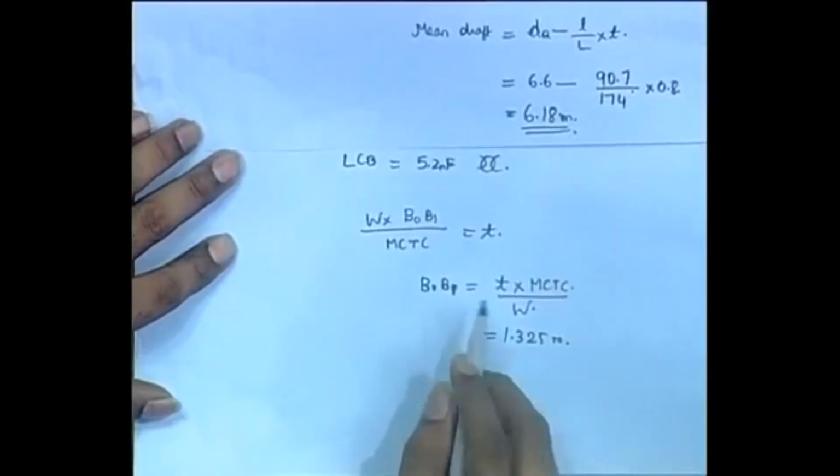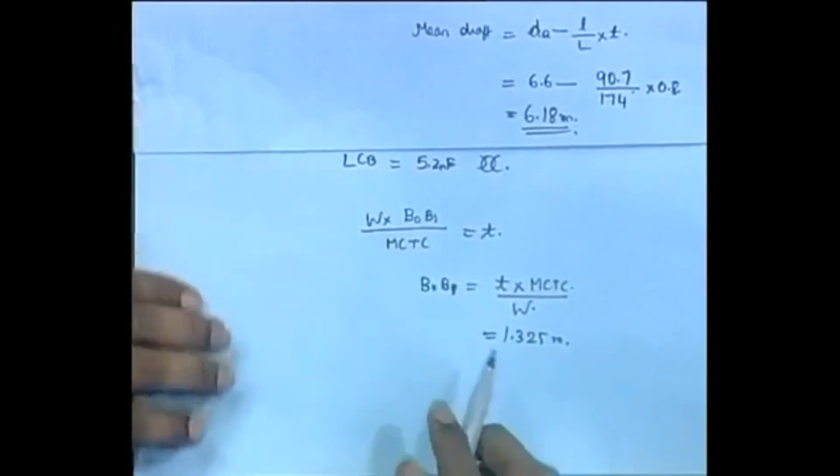So, these things you have to check while you are designing the ship, so that the ship is initially at the design draft. This is how you design a draft, for instance. This is the only way. You put weight equal to buoyancy, and you get the draft that the ship should have when it goes into water of this density. The same thing is happening here. The ship has now come to some stable state.